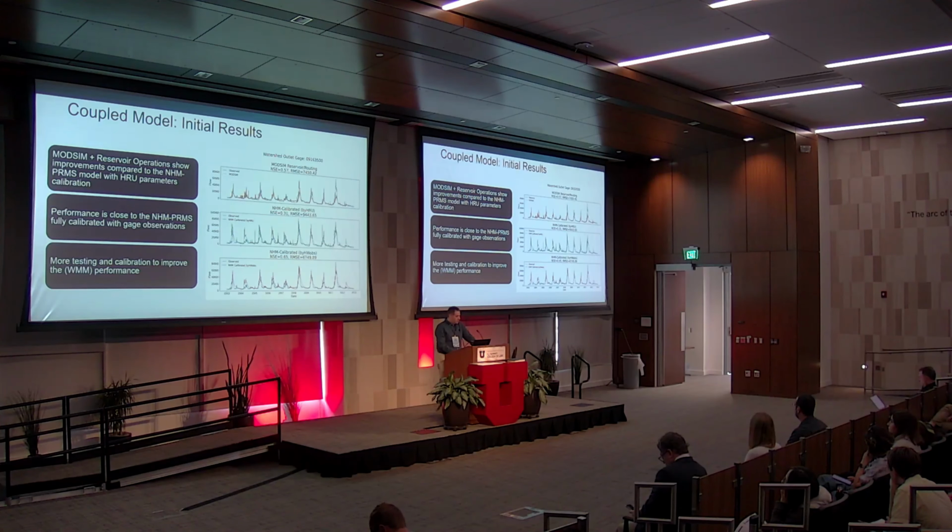Initial simulations suggest that the MODSIM coupled configuration improves performance relative to the by HRU configuration, and in several locations produces performance that is close to the by HWObs configuration, despite no calibration and only adding reservoir operations. We believe with additional testing, adding diversions, more robust routing, and calibration, we can refine the coupled framework performance while accounting for the realistic water management operations that happen in the watershed.